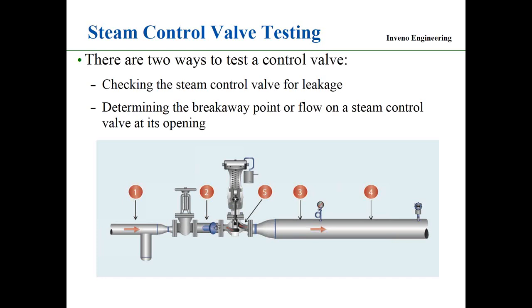Now, the same thing with this technology applied to steam control valves can be applied to utilizing a hydraulic, internal hydraulic leakage, and other valve applications outside steam. I'm just talking about steam today, okay? So those are some of the applications that you have using it. The thing is no internal steam valve leakage. Then we don't have to worry about premature valve failure, because steam leaking through a valve, steam will wire draw the seat area and the valve mechanism, the plug or whatever.